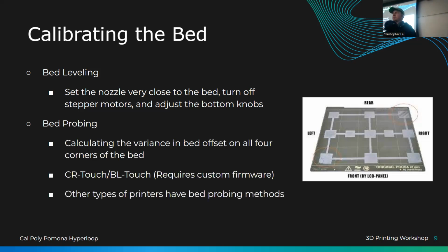There is also the idea of bed probing, which is what me and Chris and kind of everybody else who's not insane does in this deal, where essentially you have a system where you know a distance between a touch probe. It's quite literally just a switch that goes through and touches various points on the bed to basically give you a variance across that bed. We call that bed meshing.